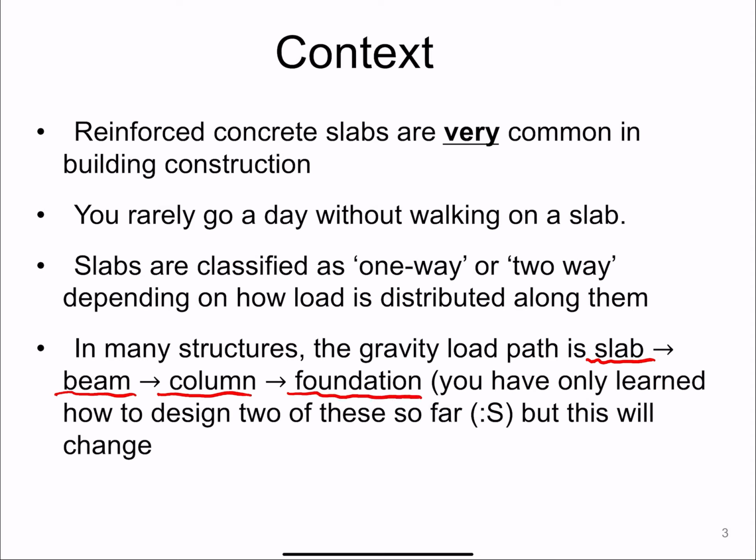Now, so far we have only done beams and columns. So when we learn slabs in this topic, either the one-way or the two-way, you will be well on your way to designing your building, because we'll do foundations later in this course, later in this term. And the only thing that you will have for a future course, in terms of basic components, is walls. But walls, rather than playing a role in how the loads get down from the floors into the foundation, provide stiffness.